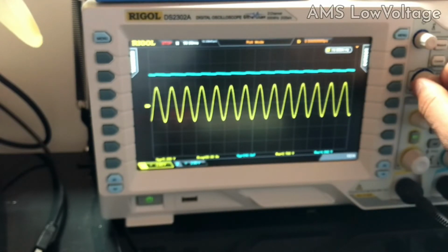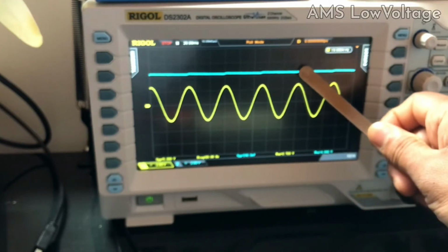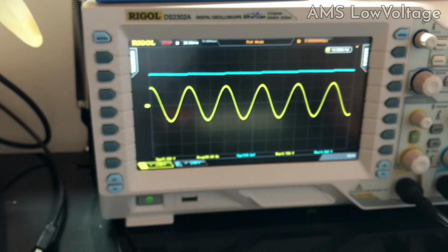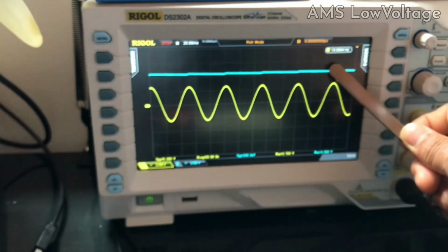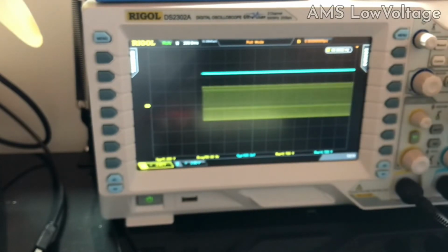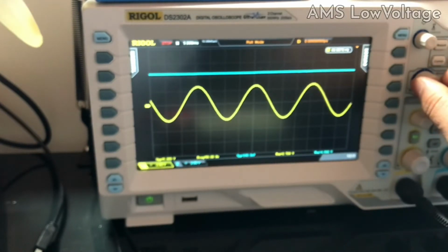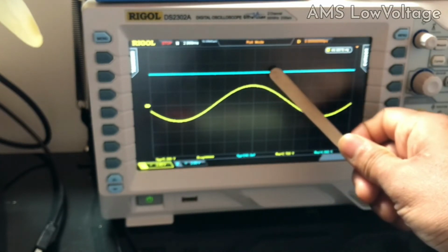So finally, from this AC input, we can get a clearly DC output. If there is a little bit of ripple on the top, if I increase the frequency more, we can get rid of the ripple as well. I have set this up now to 50, you see, for 50, there is no ripple, just a complete DC line.